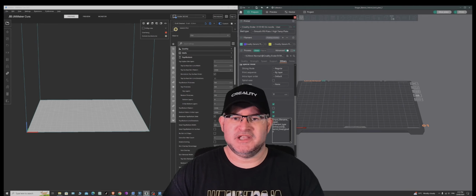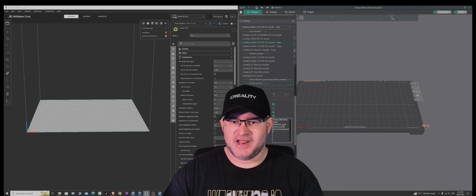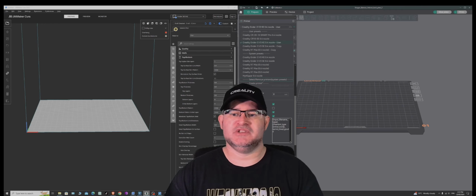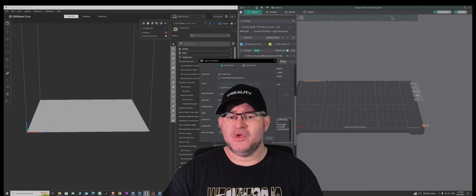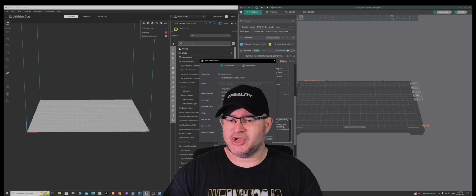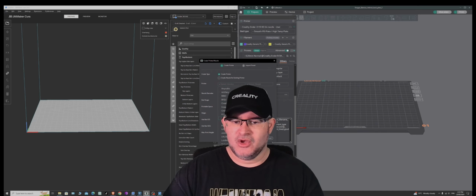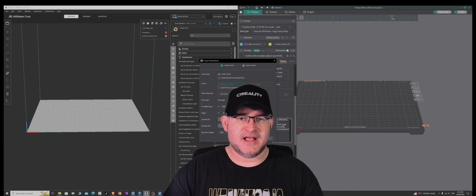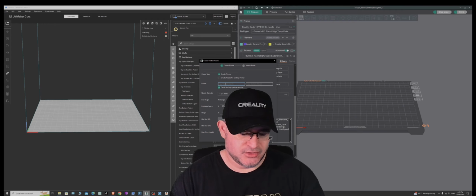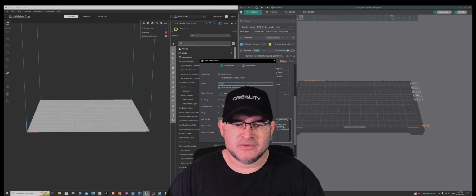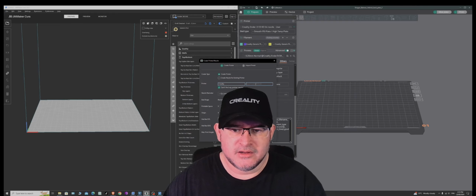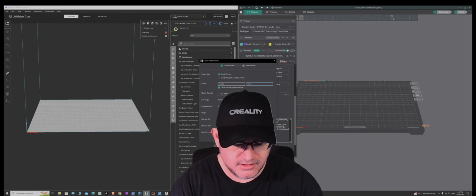All right, so we've got a printer here. We want to go into the drop-down box. We want to create a printer. So instead of selecting remove printers from the system presets, which is what we were just in before, go to custom printer. And from here, you can try and find your printer manually. If you wanted to, you can enter Creality or whatever list of printer you've got there. Now, for our sake, we're not going to do that, just so we can show you the custom way of doing it. So we'll go can't find printer model. And then we're going to enter the manufacturer's name of the model, which is simply Creality. So we'll just type that in. There's Creality, oh, I missed an L. There we go. And then we're going to input the model. For us, it's the Ender 3-SE.